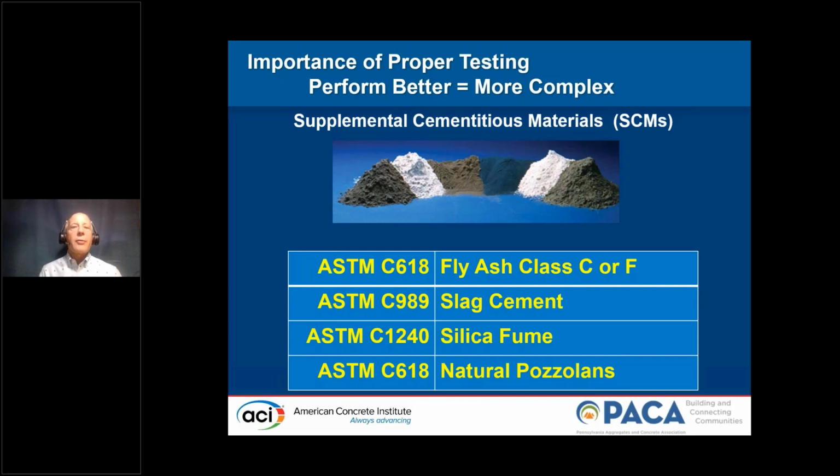Yes, they improve the strength of concrete more or less, some more than others, but we primarily use these to increase durability and reduce permeability, and they also present us with some other benefits. They really help concrete's ability to resist attacks from sulfates, as well as preventing some unwanted aggregate reactions. So we use them. It gives us durability, it gives us increased performance, but there's an added level of complexity.